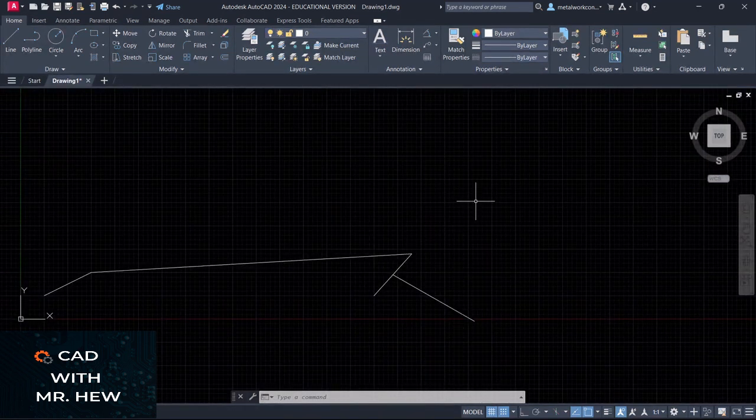Now we can enable dynamic input, meaning at the cursor, here my cursor, the dynamic input is turned off. So we can turn it on by pressing F12. So we look for F12 on our keyboard, and depending where it is, there will be the top set of keys, and sometimes you have to press function to get it. So I'm going to press mine.